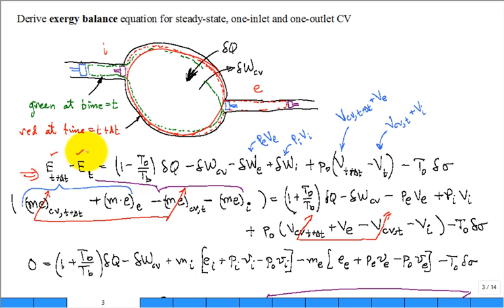This is exergy. Exergy at the initial state 1, but instead of calling it state 1, we'll put a subscript t because we're thinking about it at time t. And then at the final state 2, we're thinking that final state's happening a little in the future, time t plus delta t. What happens is you have a little transfer of heat, because this is a small delta t. You have a little transfer of heat. With it, in comes some exergy by that equation.